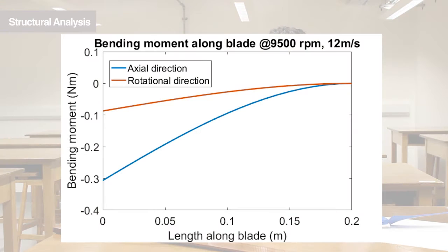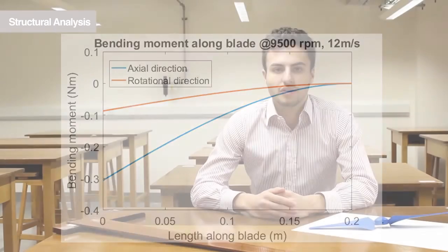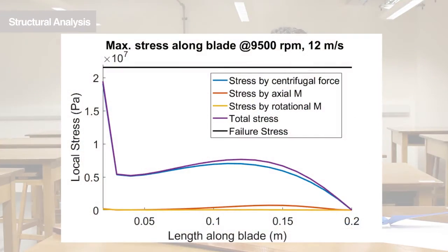Using simple beam theory, we integrated twice the aerodynamic loads distribution to get the bending moment distribution along the blade. We estimated the maximum stresses in the horizontal and vertical direction occurring on the blade surface due to those moments. We then calculated the centrifugal stress distribution along the blade, which was found to be vastly superior to the stresses due to the aerodynamic loads.